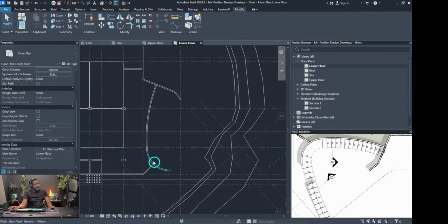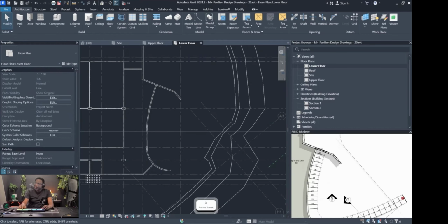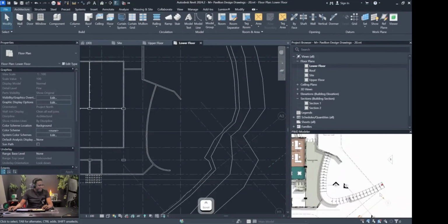All right. Now, obviously, this is going to be a custom stair. So in order to get a custom stair, we are going to need to use some specific stair features. Before we jump into our stair tool, whenever we're doing this type of stairs, which is going to be a highly customized stairs, it's a good idea to sketch out our stairs first using line work, and then we use the stair sketch tool and just trace those lines. So let's figure out how we would draw these stairs here.